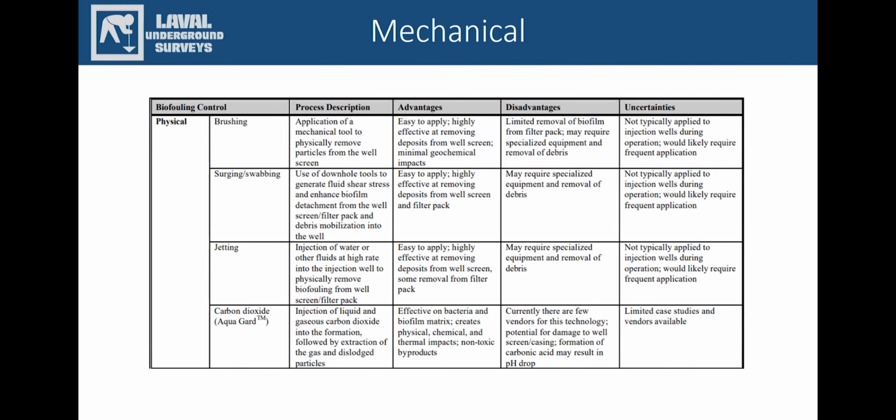There are many different ways of treating a well mechanically, and it can be useful when treating it for biofouling, as typically one treatment option alone doesn't give a sufficient clean. Brushing and surging can give good cleans when used with chemicals. Alone, they're not able to penetrate the filter pack, but when used with chemicals, they'll push the chemical further out into the formation and clean the filter pack, and possibly further. This allows for a longer clean.